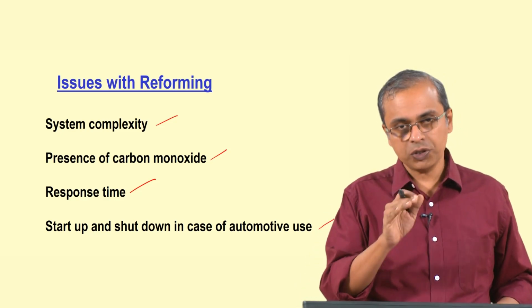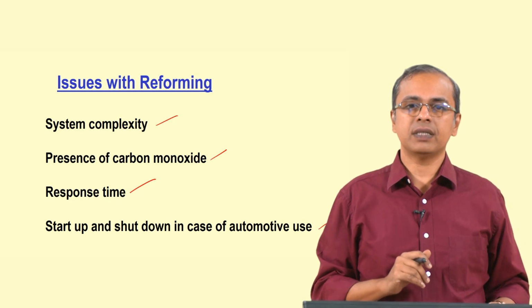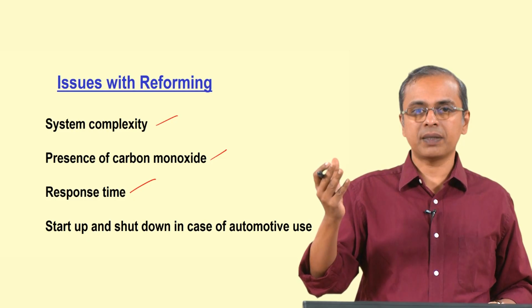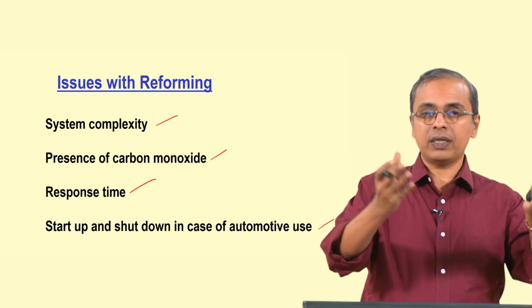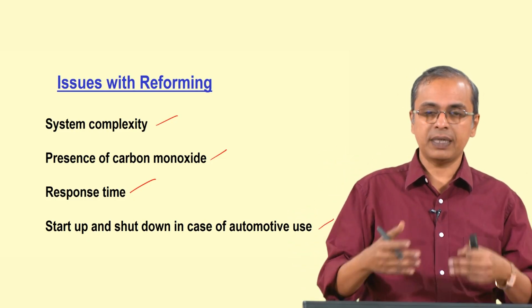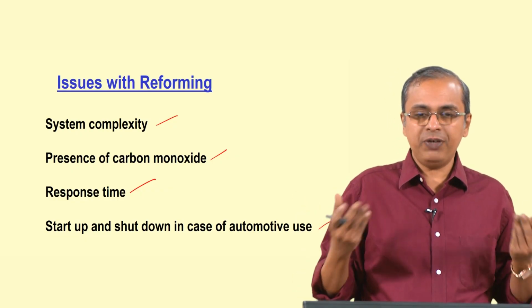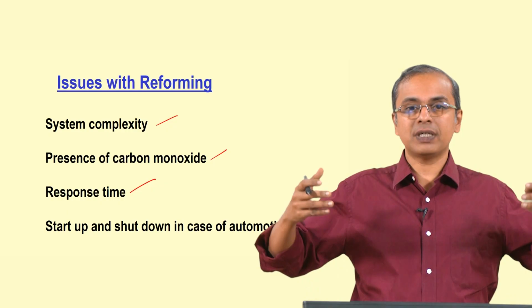So, startup and shutdown also sort of are associated with this response time, because when you start up suddenly from a cold start, a lot of gas has to enter all the reformer locations of the reformer, get reformed, get ready, get into the fuel cell and start. And we being who we are, we want the vehicle to start immediately.